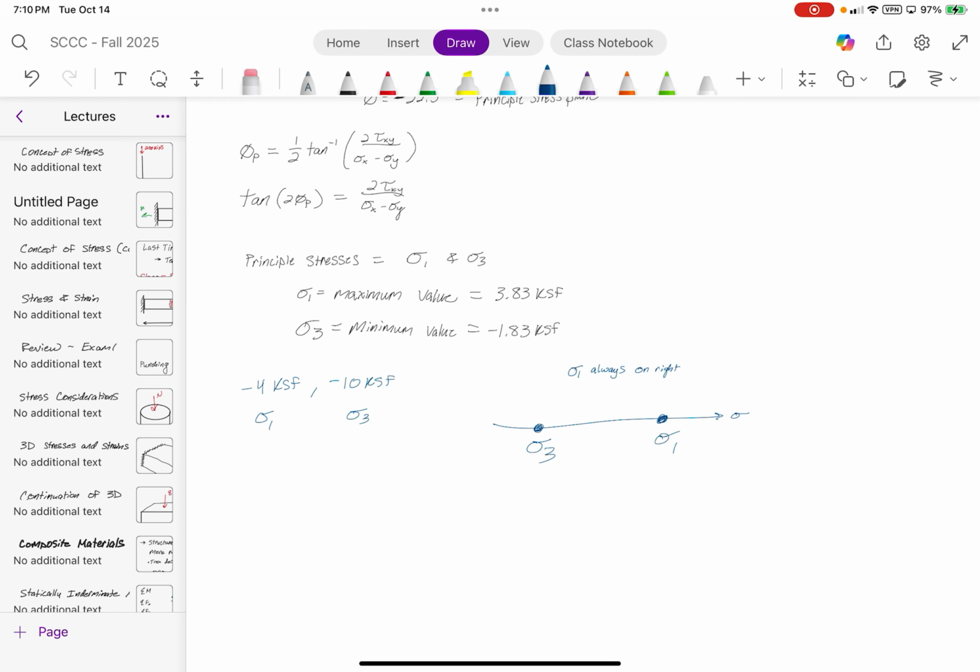So all you need to do is find out how the stress of the steel and the aluminum relate. So how much more force is the steel going to attract than the aluminum? So just do the proportion. What is this entire thing times PST, and then what is this entire thing times PAL? I have to multiply this by PAL. Oh, wait, I think I remember this now.